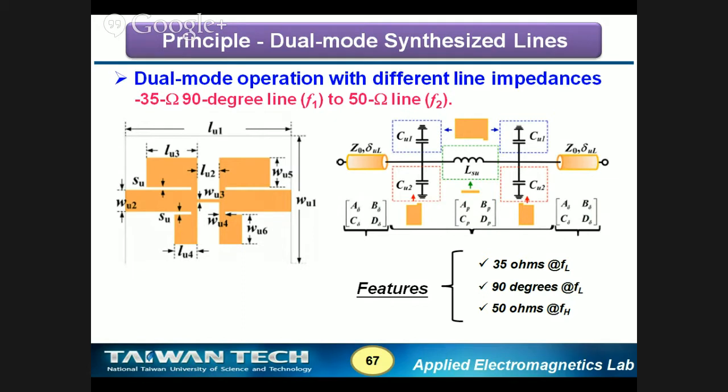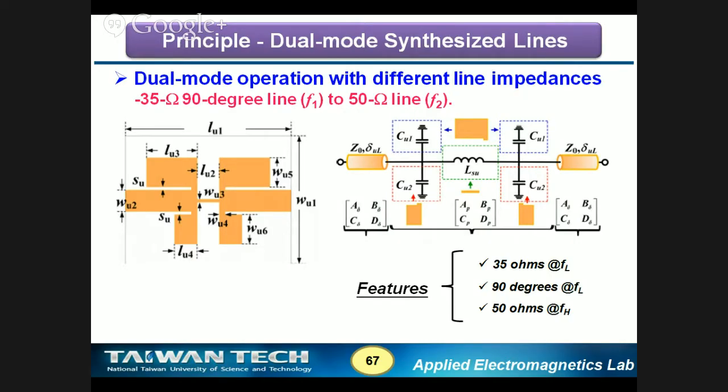But if you design it using an integrated process, which I will introduce with an example later on, called the integrated passive device process, IPD process, there is in general a good mapping between your inductance value and those realized using the real physical footprint, because the size is very small in terms of wavelengths, since the chip is very small.